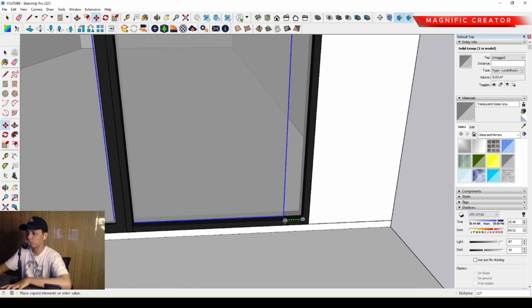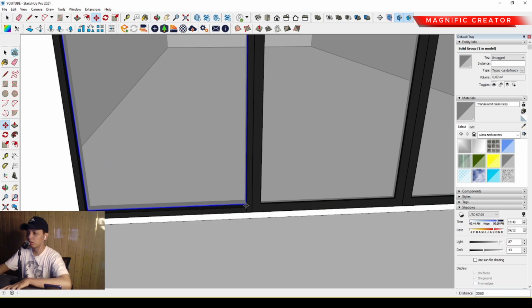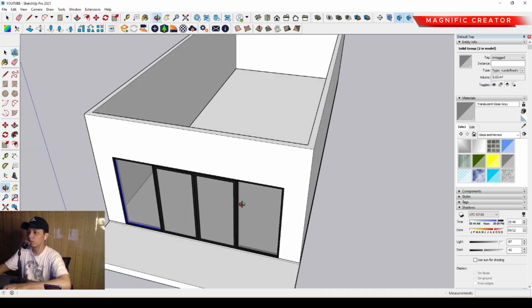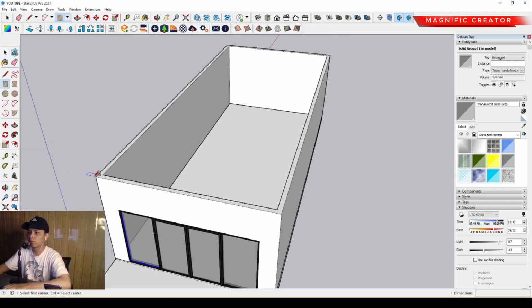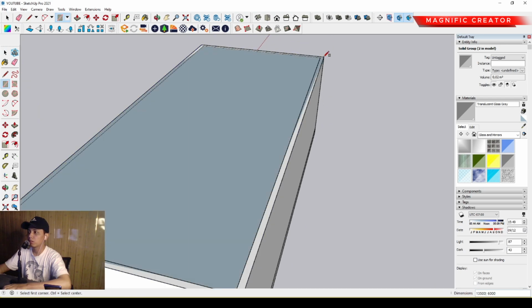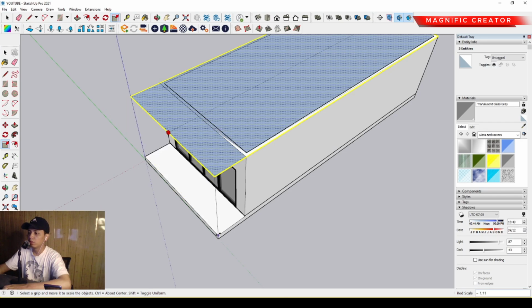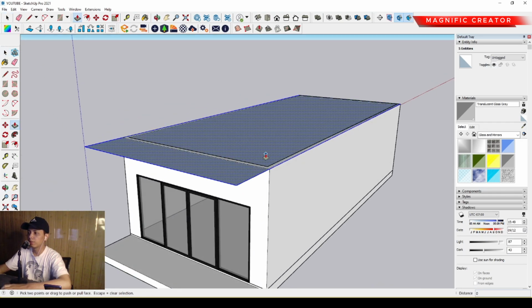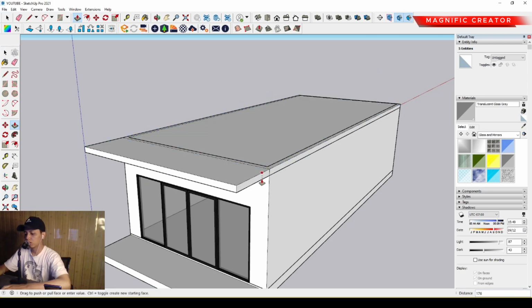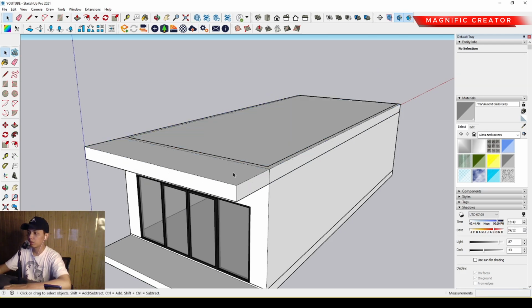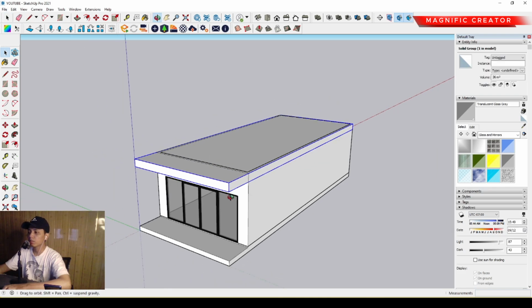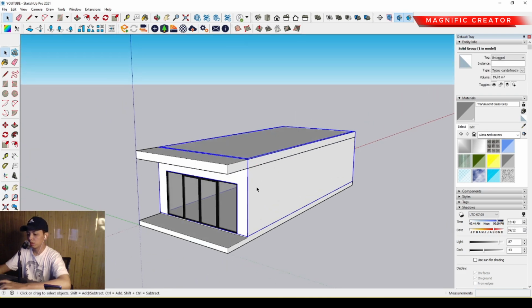So then we can move it and duplicate it to another position. Okay, and then we can make another floor, a second floor, with a slab with a rectangle. So then we can select it all and select the scale, move it, and drag it forward. Then we can push it down around 400 millimeters, just for example. And then we can make another wall on the second floor.